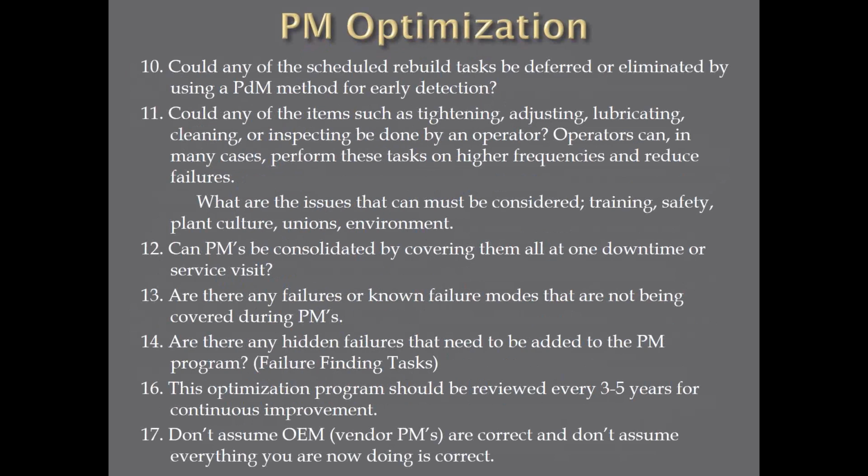I was at a plant one time where they hadn't checked the emergency stops in this department for 14 years. When they tested them, they'd been wired wrong since day one. But because we never had to use them, never tested them, if they ever were needed, they wouldn't have worked. Failure finding task.